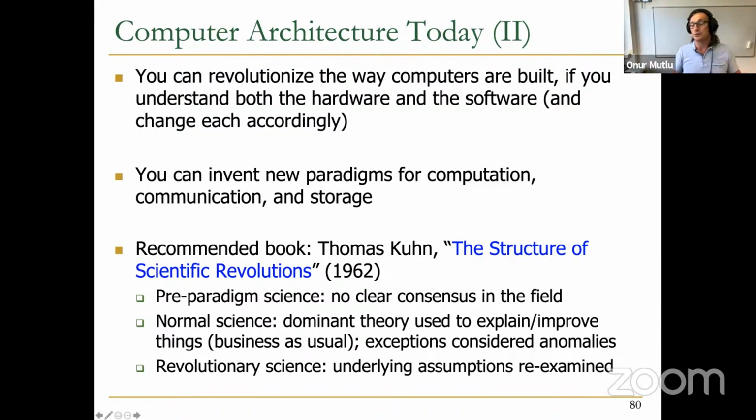So, like 20 years ago, let's say, the dominant theory, let's say dominant practice, I will say in this case, was to actually design single core processors, heavily pipelined or reasonably heavily pipelined, increase the frequencies, increase the pipelining level, and you have a general purpose processor, superscalar, out of order processor with heavy branch prediction, etc., heavy caching, and that's considered the best way of designing computers. Now that doesn't exist today. People have poked so many holes, so many exceptions against that practice, and they have shown that, okay, this is not energy efficient, this is not high performance enough, this is not secure, etc.